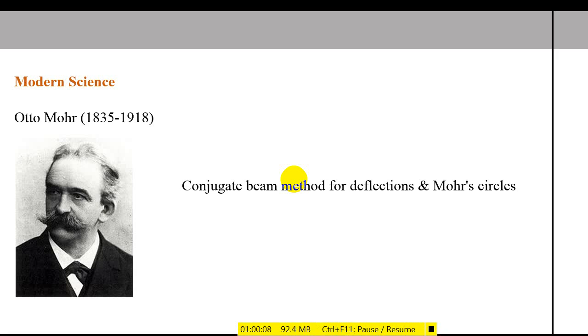So within that 50 years, it should not demonstrate excessive cracks, it should not demonstrate excessive deflection, it should not have a high vibration feeling due to external factors. External factors are loads. So if that's so, then the building is serviceable during its service period. So for every building, every structure, every equipment, you have a service period or serviceable life.